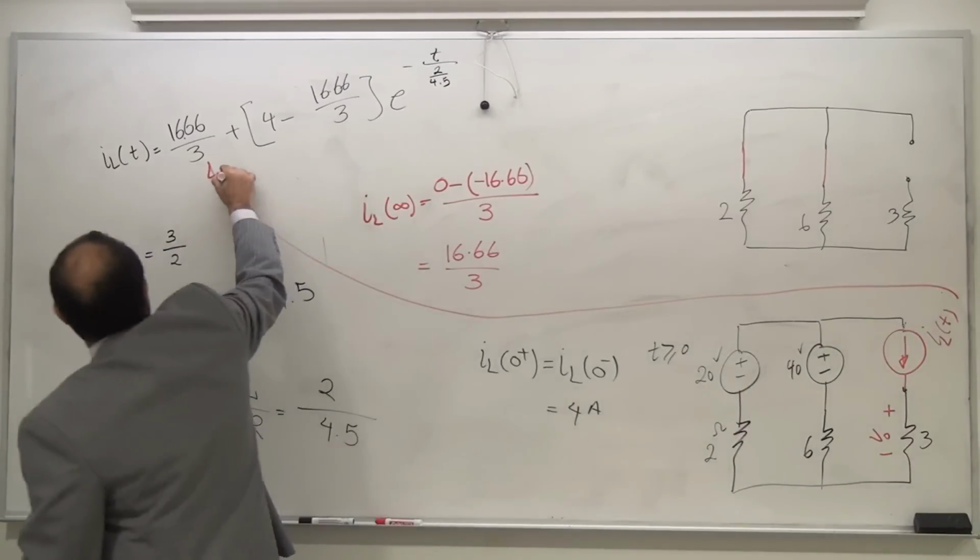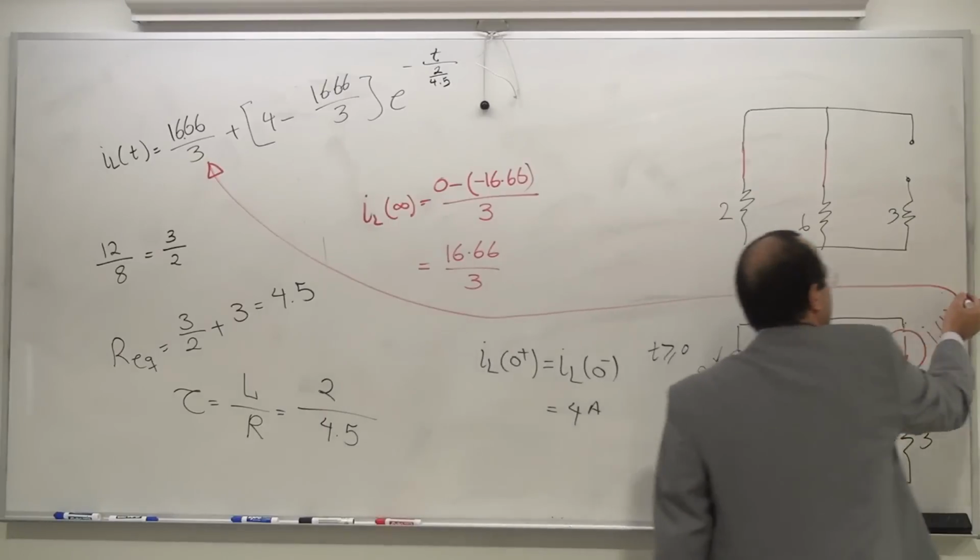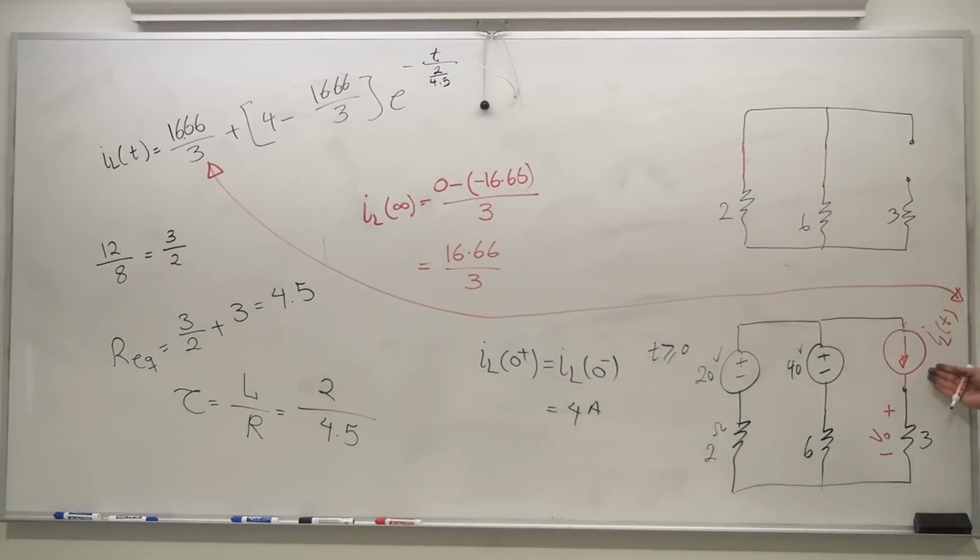This is the function. The function is not a DC anymore. But if I have this as a function in my design, then of course this voltage will be 3 times this. Or if you want this voltage, you just have a simple system. You just do node or mesh, whatever you like to do. You find this voltage, you find this current. It's relatively a good shortcut. Sometimes it works faster than the regular one.